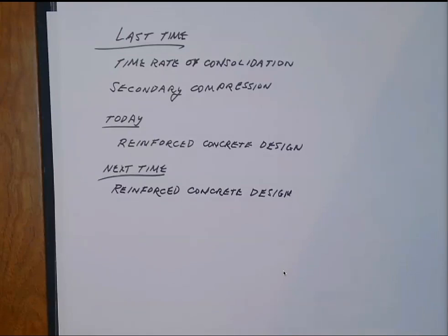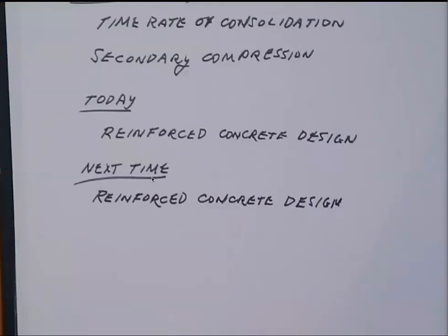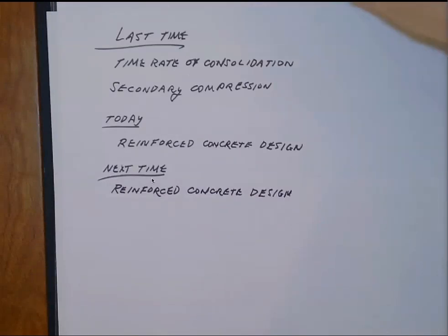That's a common type of calculation that would be applied in the field. We also looked at, oh boy, that's not behaving, secondary compression. And that assesses a creep mechanism in soils, which would be a continual compression occurring, assumed to occur after end of primary. So after that little knee in the curve that is showing up on a void ratio log time plot. And the slope of that does show up as a C sub alpha.